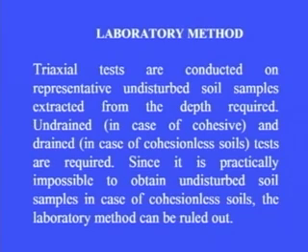Laboratory method: triaxial tests are conducted on representative undisturbed soil samples extracted from the depth required, undrained in case of cohesive and drained in case of cohesionless soil. Since it is practically impossible to obtain undisturbed soil samples in case of cohesionless soils, the laboratory method can be ruled out.